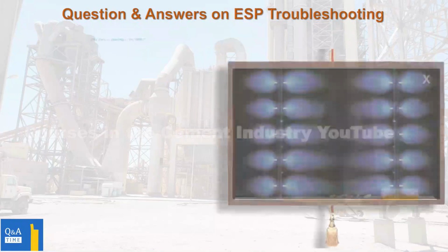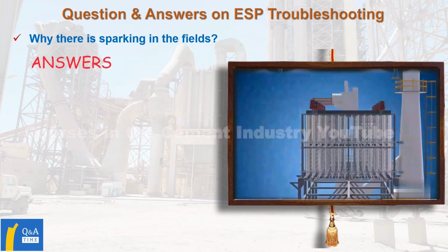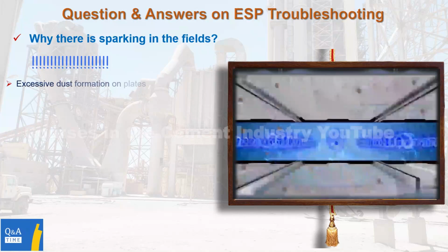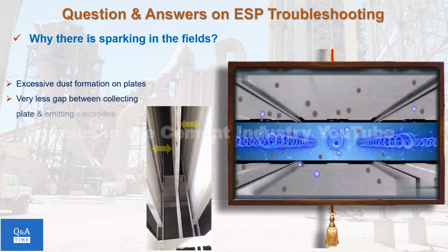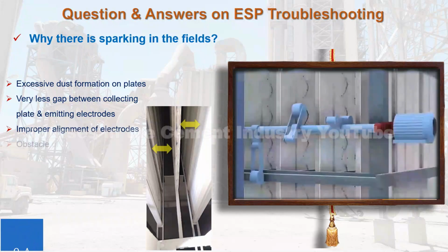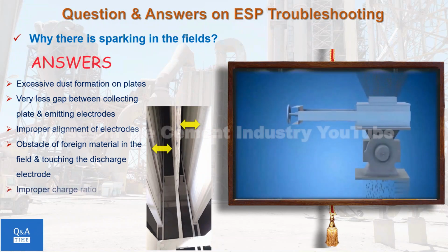Question 2. Why there is sparking in the fields? Answer. 1. Excessive dust formation on plates. 2. Very less gap between collecting plate and emitting electrodes. 3. Improper alignment of electrodes. 4. Obstacle of foreign material in the field and touching the discharge electrode. 5. Improper charge ratio.